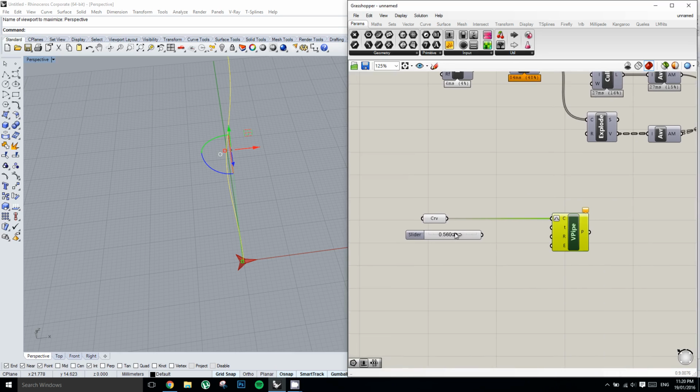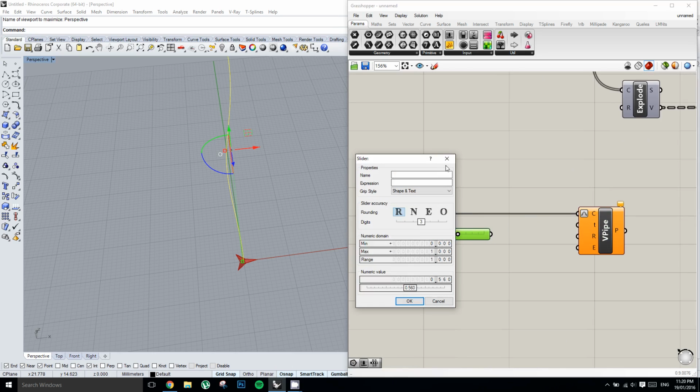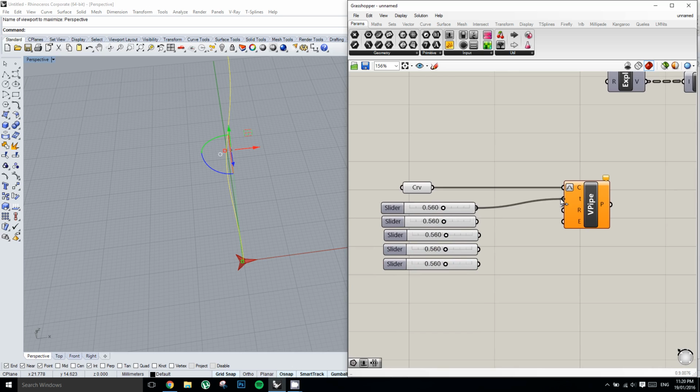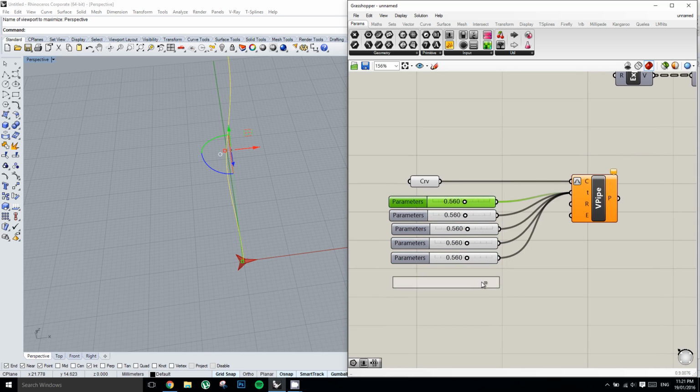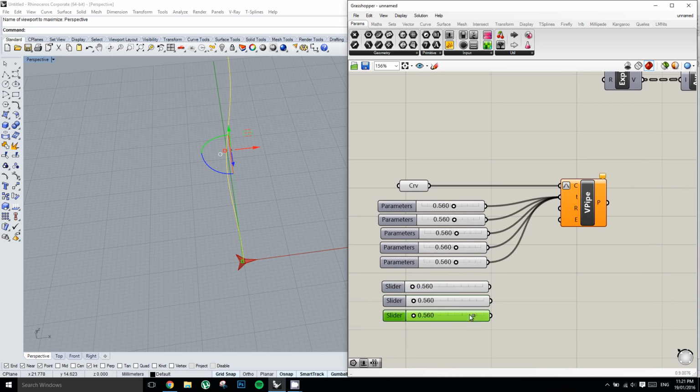I'm going to make 4 copies of, actually, before I make those copies, no wait, hold on. Okay, those are going to be my 5 parameters. I'm also going to make 5 radius values. For a radius we might want a max value of, I don't know, let's set it to 20 for now. And we'll also make 5 copies of that. You'll notice our variable pipe component turns red at the moment, but as soon as we plug the correct number of inputs in, we're away laughing.